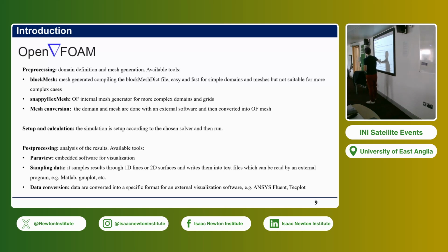For post-processing, OpenFOAM natively uses ParaView. So there is a ParaView installation in the virtual machine I provide. I always use ParaView for visualization. You can, of course, sample data over lines, over surfaces, and extract them and load them with Python or MATLAB, which is what I'm using. You can, of course, convert your OpenFOAM result into a format that is, for example, possible to open in Tecplot or even in ANSYS if you want.